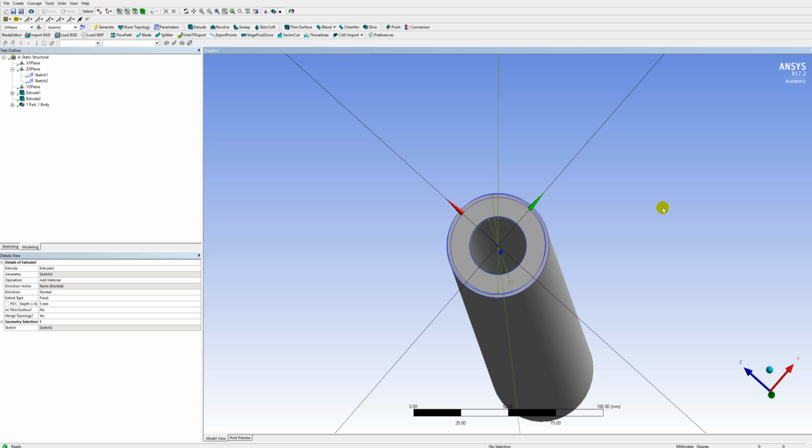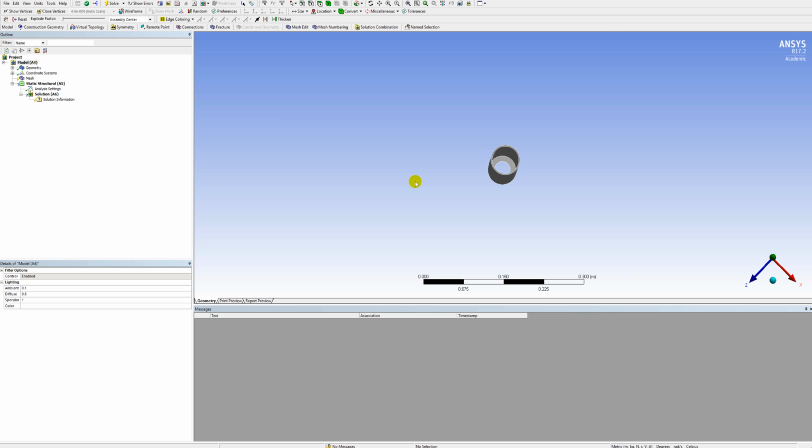Before we cut to the next segment, pause the video and launch the model step. For this simulation, I'll go into meshing in more detail. If you try and generate the mesh right away, the mesher will definitely get stuck and probably use up all of your RAM and crash the program. This is because it can't handle sharp edges very well.